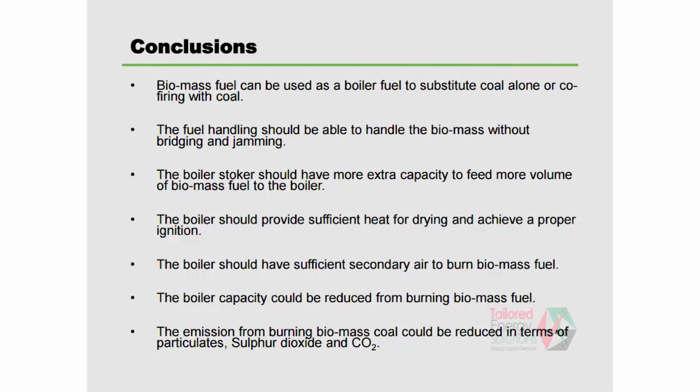I think the conclusion, you know what I want to say now. Biomass can be used to substitute coal. For the coal handling system, we need to consider whether it is able to handle biomass or not. The boiler stoker should have enough capacity to handle the large volume. The boiler should have a way to provide sufficient heat for drying the wood fuel.